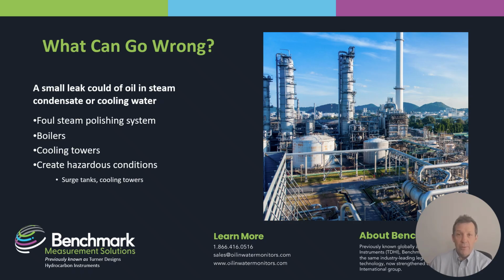It could become fouled. The heated boilers themselves could become fouled with the oil or hydrocarbons, which could cause corrosion or overheating of different parts of the steam boilers. And then if any of that fuel or hydrocarbons get into the cooling towers, those could be fouled in a very different way, but that could also cause hazardous area conditions.